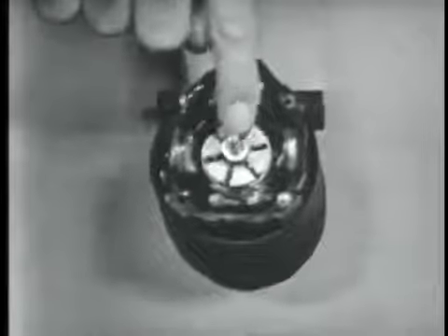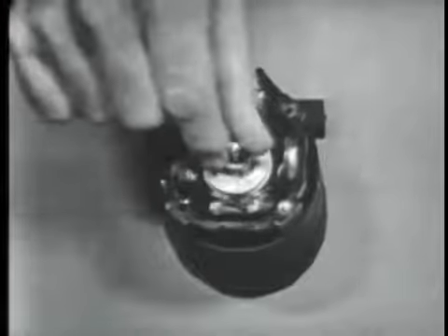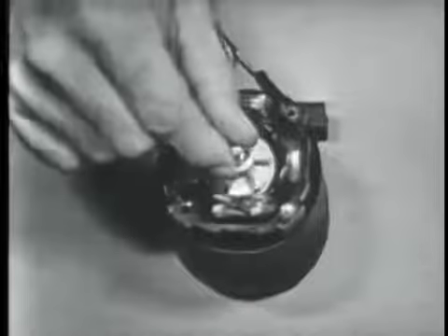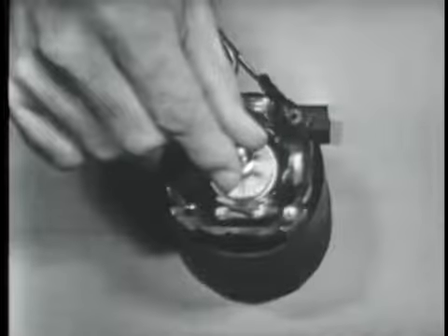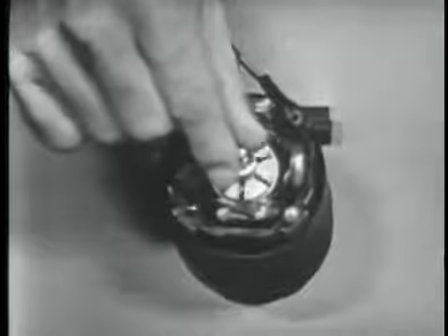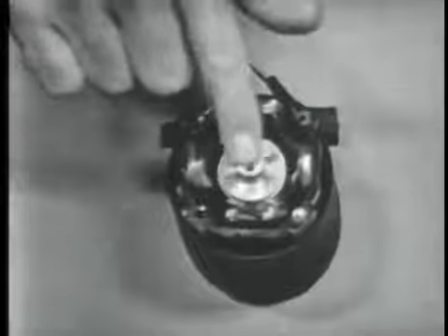One, the internal load, that is rotor weight, the little fan, the bearing friction, and so on, and the external load on the motor, such as the gears, pulleys, or the fan blade, or in this case, my finger. As I squeeze it a little bit, you can see that it turns slower, whatever work the motor must do. So the rotor has got to go slower than the rotating magnetic field in order to have relative motion so that it can become an electromagnet.